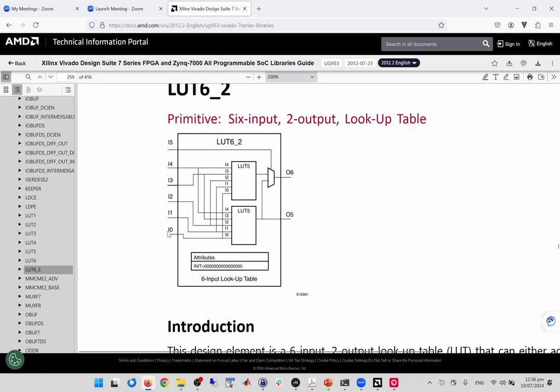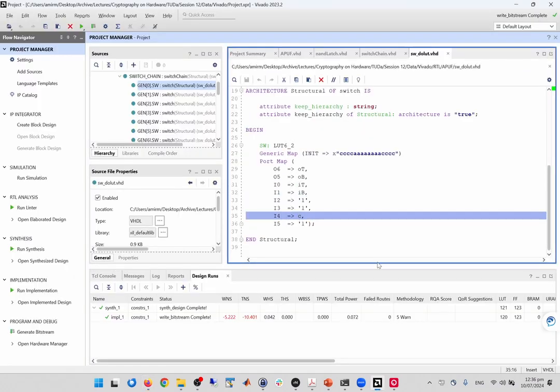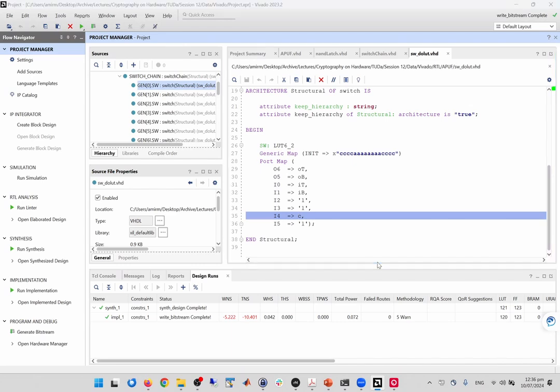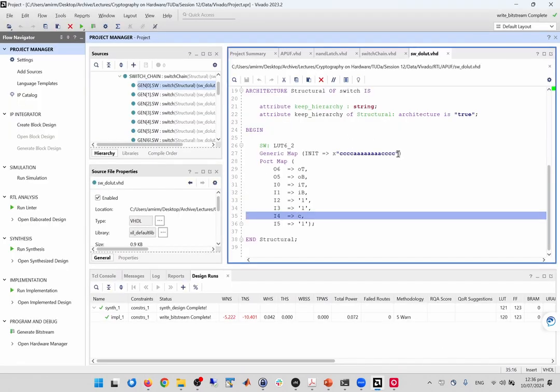I0 and I1 are connected to both LUTs. And then one challenge is actually connected to I5, to I4, which is also the last bit of here. The content of the lookup table is built in a way that what appears at I top appears on output top, and what appears on I bottom appears on the output bottom. That means this is exactly pass through.